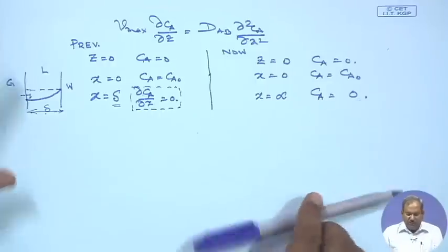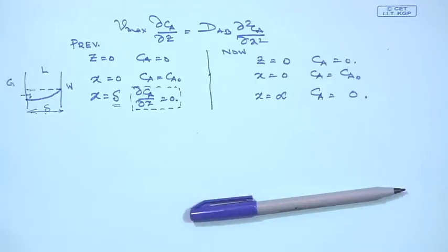that Ca is going to be equal to 0, which is true, because if this is the thickness of the film, A molecules are only very close to this point, because they cannot penetrate much. So, whatever happens at a point far from the interface is, mathematically speaking, at an infinite distance as far as the A molecules are concerned. And what is the concentration of A in here? It is 0, nothing. No A exists at that point, since A exists only up to this point.